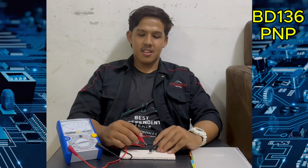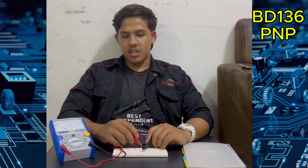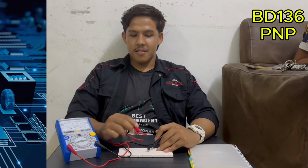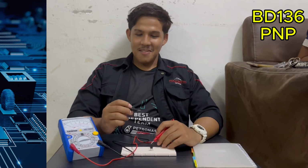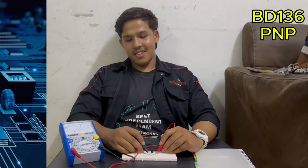Okay, next I will detect the collector and emitter terminals. First things first, I will change the range to times 10K. Now I will put the black probe to the middle terminal and the red probe to the right terminal. We can see the value is infinity. That means the middle terminal is the collector, because the collector has a higher value than the emitter. Next, to make sure that is true, I will put the black probe to the right terminal and the red probe to the middle. As we can see, the multimeter is reading. So that means the right terminal is the emitter.